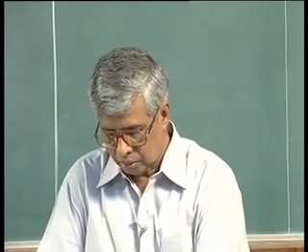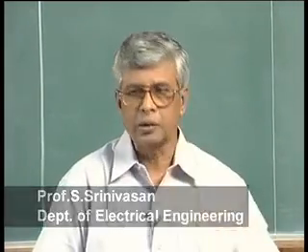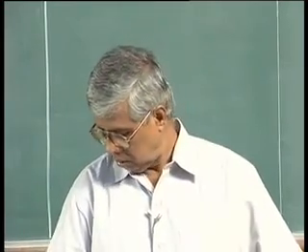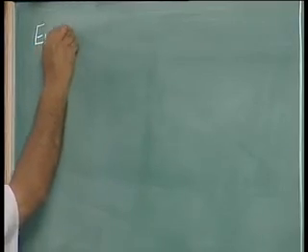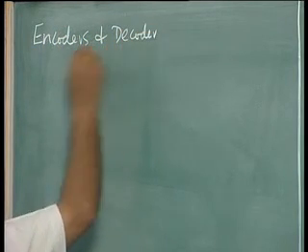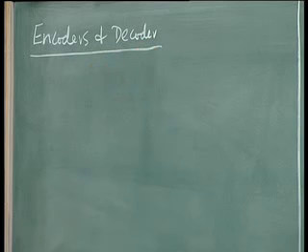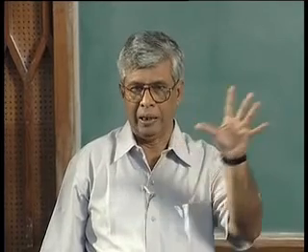So, in the last lecture, or maybe last two lectures, we talked about multiplexers in detail and how to use them as building blocks or functional units in design of combinational logic. Today we will see another MSI circuit, which is a decoder. First we will see what an encoder is and then a decoder, encoders and decoders. As the name suggests, one codes the various combinations into a smaller number of bits, the other expands it back.